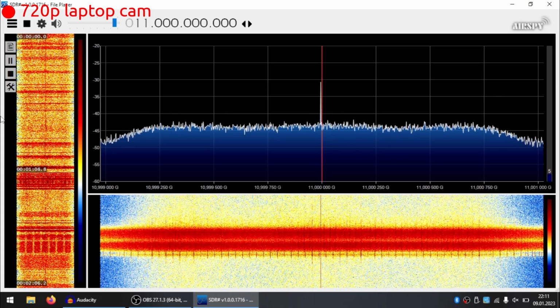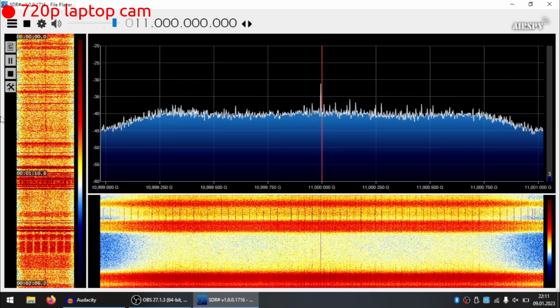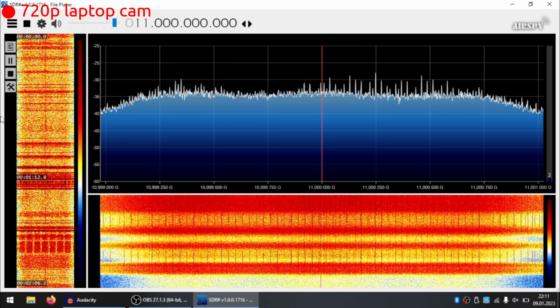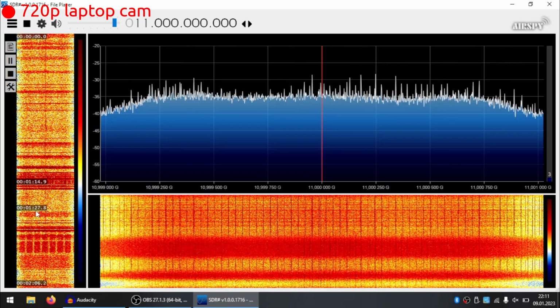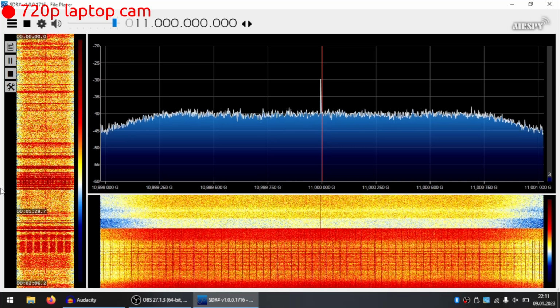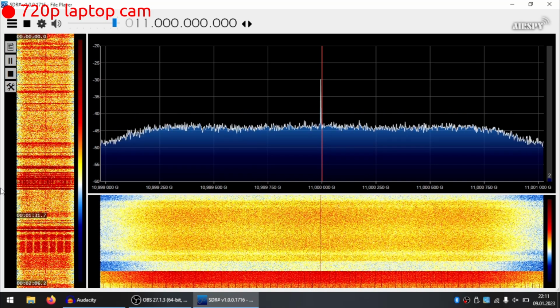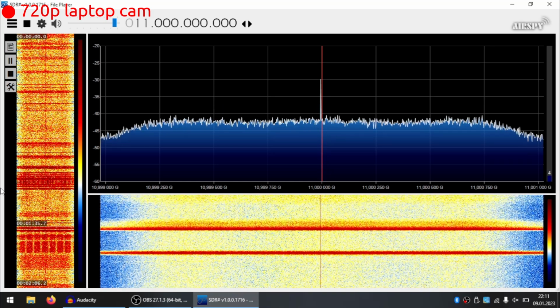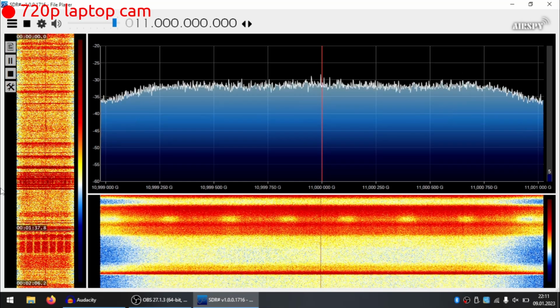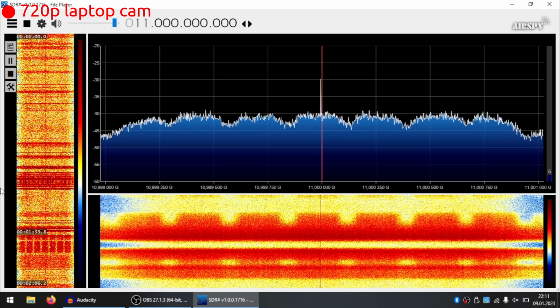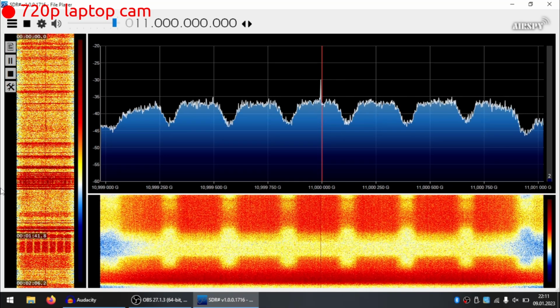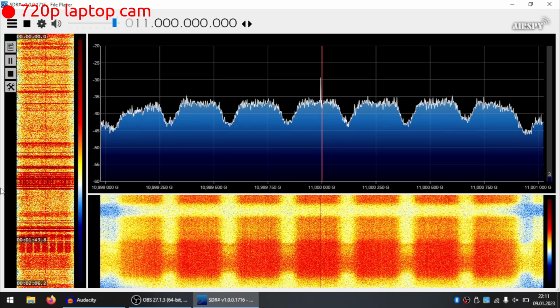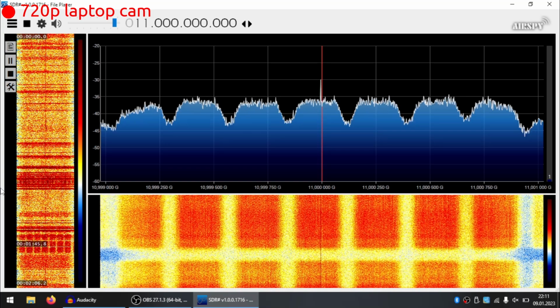In terms of artificial sources, Ku-band TV satellites are so numerous and omnipresent that simply aiming the dish at any random point in geostationary orbit will result in many signals appearing on the spectrum. These usually tend to be very wide, even over 20 MHz in bandwidth, so an RTL SDR v3 which can only sample around 2.5 MHz would also perceive those only as an increase in the overall noise floor level. With a bit of searching though, you will eventually uncover some narrowband transmission.